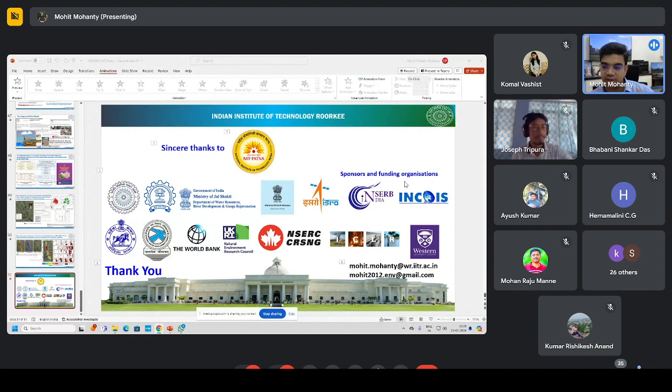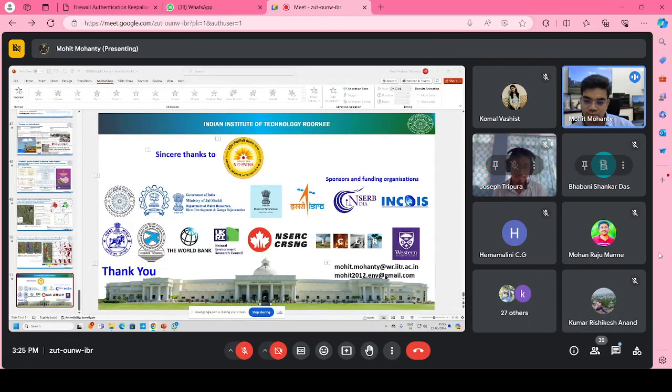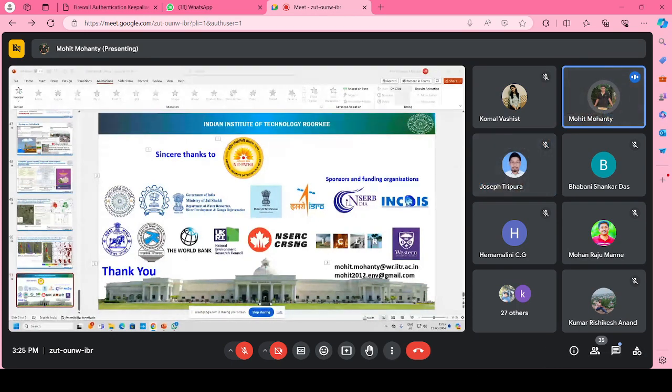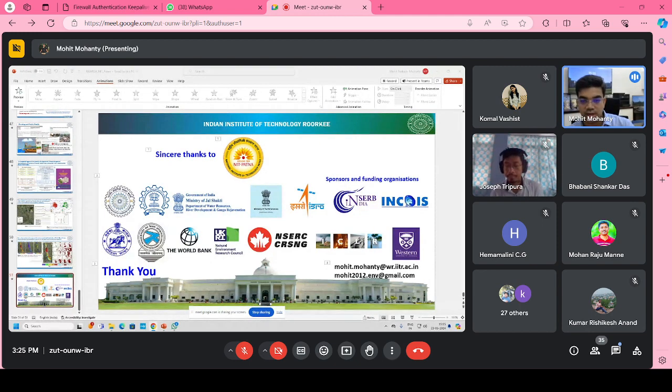Sea level rise is not a very dynamic component, but when we create the flood model, we should also input the sea level rise along with the storm tide data. Storm tide data is more dynamic, and it will enter from the sea towards the landmass through the mouth of the river, or affect the land just connected to the river.